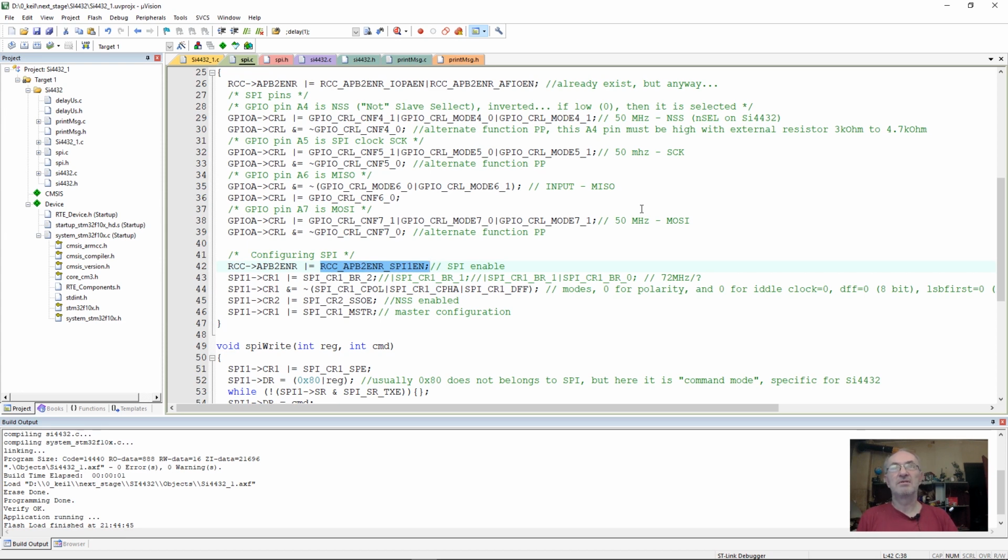This is because of a security measure. If we have 2 masters, for example this transceiver, this is not a sensor, it can be used by 2 microcontrollers. In this case, this wire can be shared by one microcontroller or the other. If one microcontroller starts first and pulls the wire down, then the other microcontroller feels that change, and if it is about to send data, it stops, immediately stops.